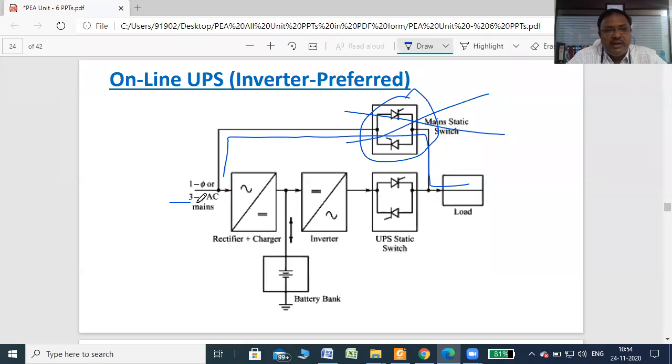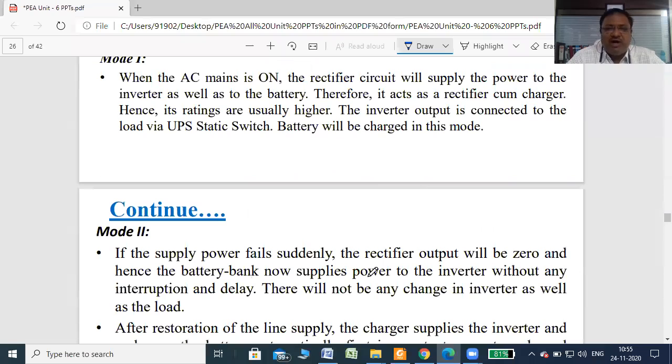So what happens? The AC voltage is first converted into DC, so voltage spikes and any surge are automatically removed. Then it is converted again into AC with the help of the inverter. If you are using a proper inverter, for example a PWM inverter, then the noise at its output is zero. The PWM inverter itself controls any high voltage spikes, because the input to the inverter is DC, so no voltage spikes appear at the output. That's why the online UPS has these advantages.